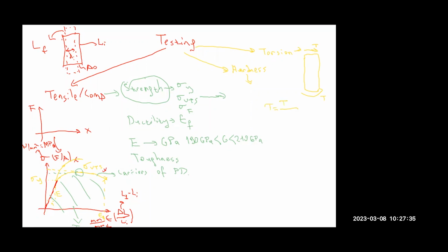We can calculate it through the amount of torque we are applying to the system, Tc over J. Then we can measure the shear stress instead of normal stress. What else? What other tests do we have?